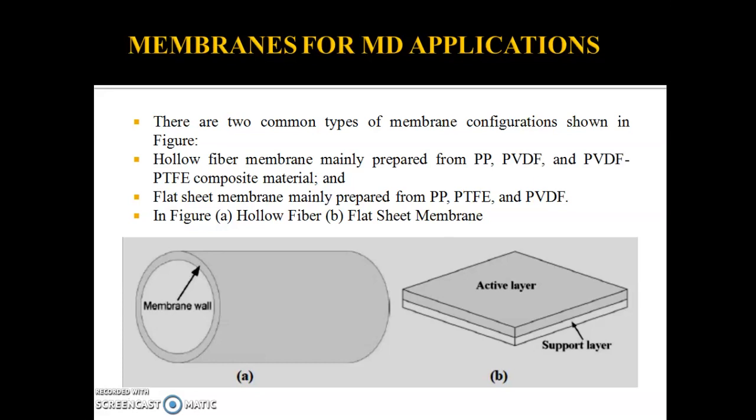The tubular membranes are also utilized in membrane distillation. Tubular ceramic membranes were employed in three membrane distillation configurations. Either direct contact membrane distillation, air gap membrane distillation, or vacuum membrane distillation, the tubular membrane can be used. It was used to treat NaCl aqueous solution also, where salt rejection was more than 99%.